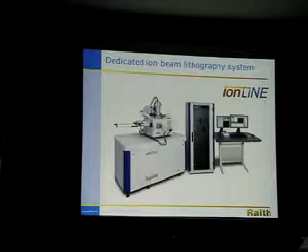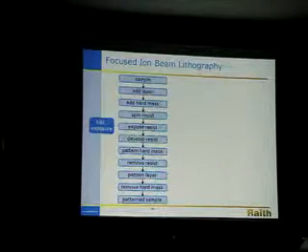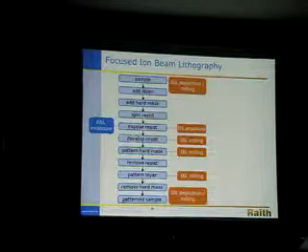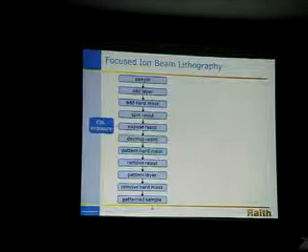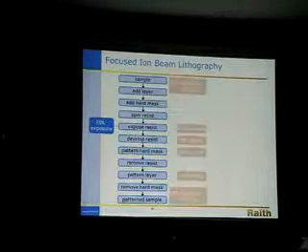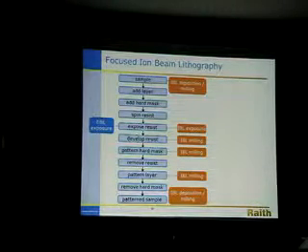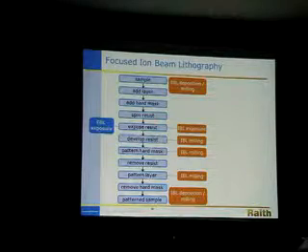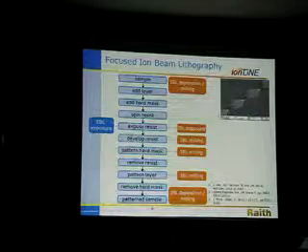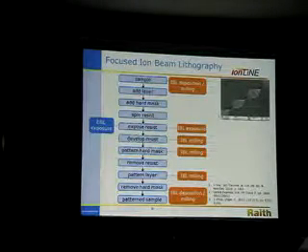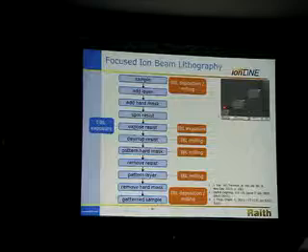The ion line is a focused ion beam lithography instrument, and focused ion beam lithography complements electron beam lithography in the following way. Electron beam lithography only exposes resist in nanofabrication, whereas focused ion beam lithography can address many different steps along the nanofabrication process. In this sense, it serves as a complement to electron beam lithography. It does not replace electron beam lithography. And so focused ion beam lithography can do 3-dimensional milling.